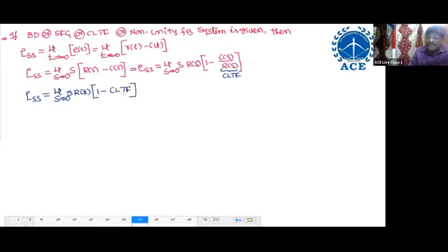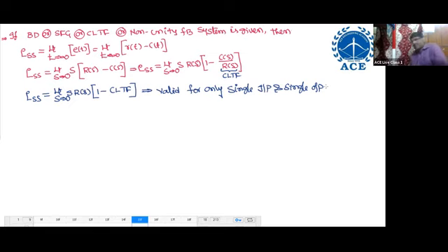But this is valid for only single input, single output systems, not for multi input, multi output systems, because for multiple input, multiple output we don't get a transfer function first of all. We write only the output. So it is valid for all the problems, even for unity feedback. But for unity feedback, better to always use the word type and input, compare and get the answer.